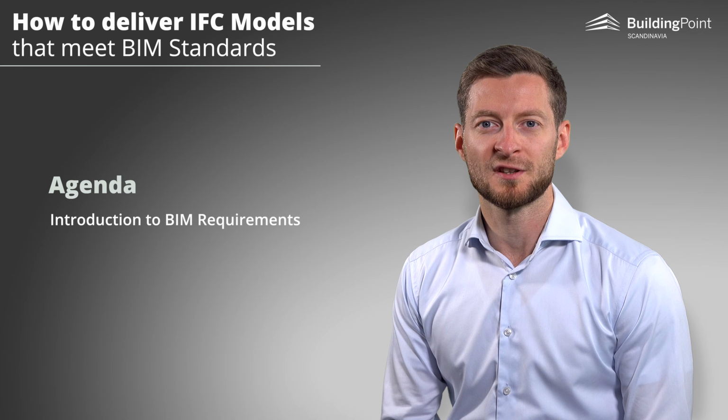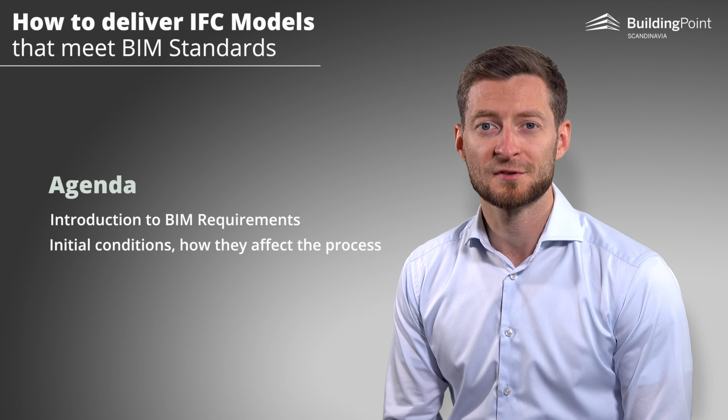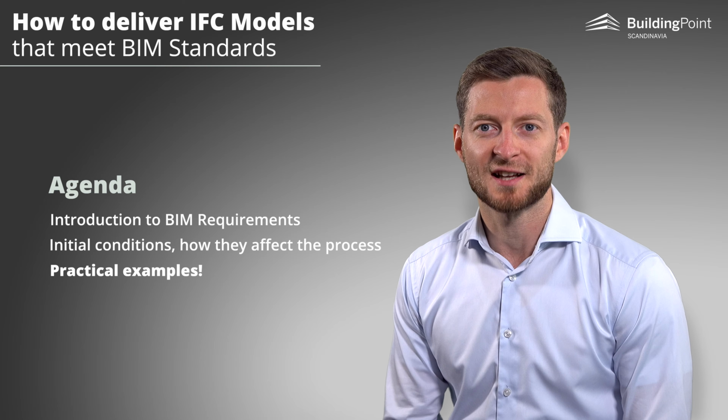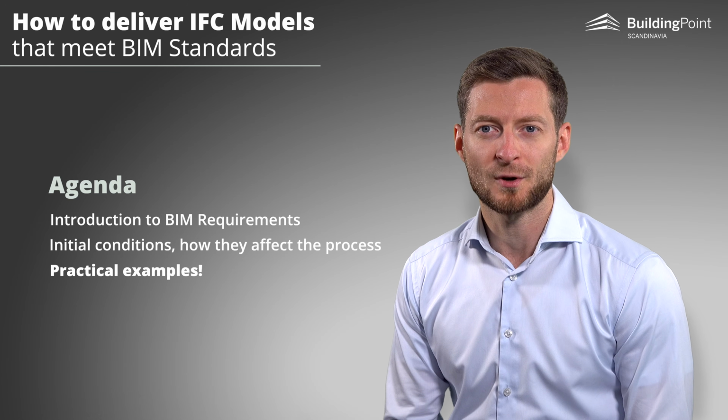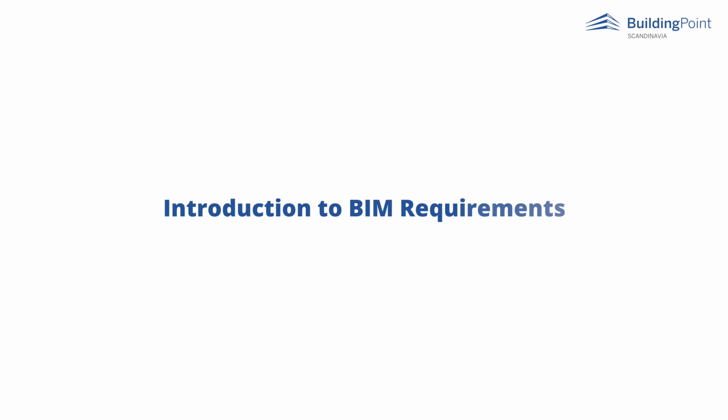We will start with an introduction to BIM requirements and the responsibilities involved. Next, we will discuss the initial condition, what you need to know at the beginning, including the impact of various factors on the entire process. Finally, the main chapter will focus on model preparation. I will show you how to prepare a model directly in Tekla, covering tasks like dividing the model into floors, adding extra information, exporting the IFC itself, and then handling the IFC on selected examples. Of course, requirements may vary depending on the project and the organization providing them.